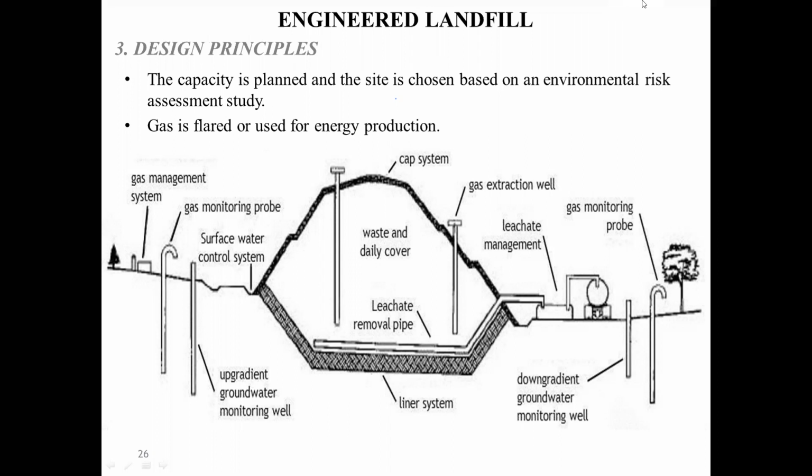The key components on which we are going to depend for our landfill are, first, a planned capacity, a site established with respect to the design criteria so that it fulfills the planned capacity, and the site chosen should be based upon the environmental risk assessment.